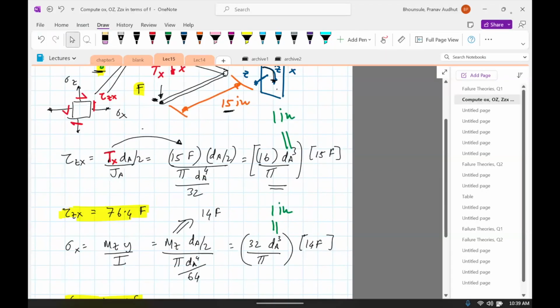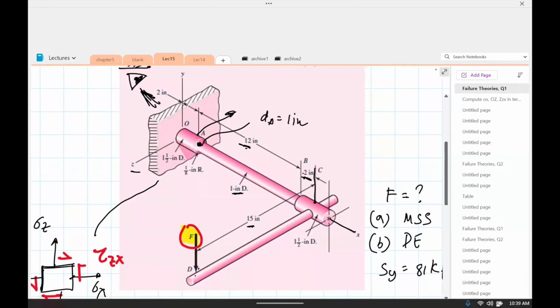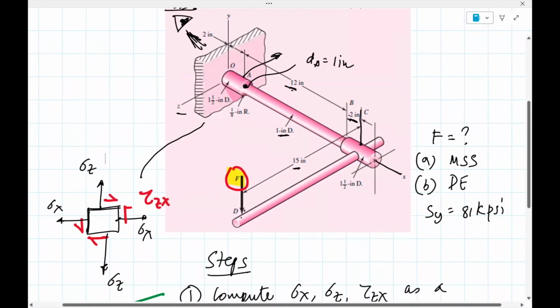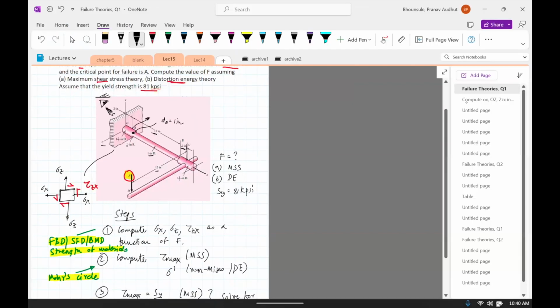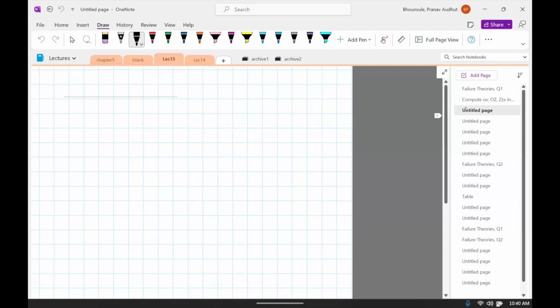Where were we? We were solving for... We're going about this. We've done one, which is, by the way, the hardest part. Let's do the Mohr circle. You can do the Mohr circle, or you can just compute it using the transformation formulas. Let's compute the maximum shear stress, tau max, and sigma prime. For that, we need to compute... So stress step 2.